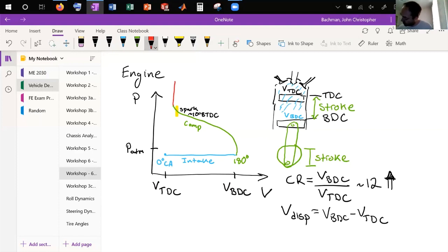And then what'll basically happen is you're going to get a spike in pressure roughly, when you have the combustion phase that happens very quickly. It's not infinitely fast because your engine's actually moving pretty fast, but relatively quick, you'll get a little spike in pressure. And this happens at 360 degrees, so you're basically back at top dead center after your compression stroke.